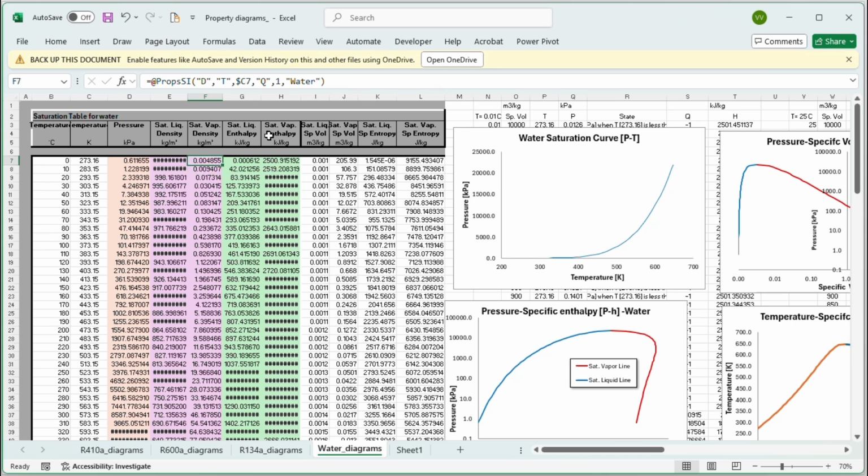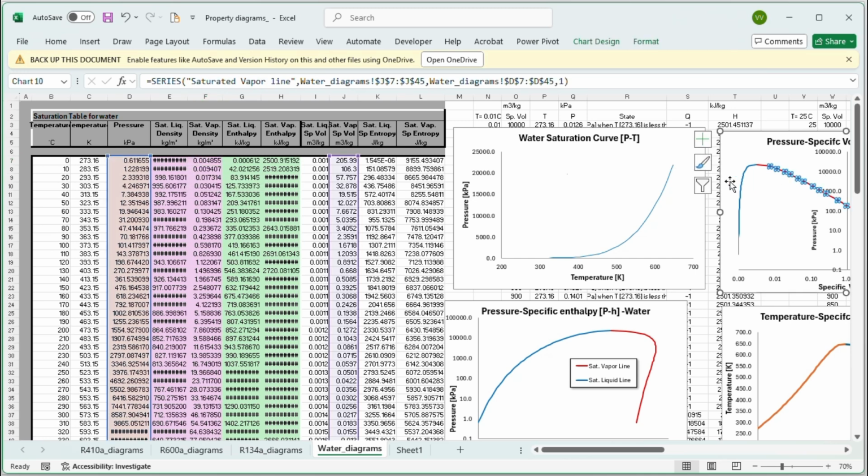And for liquid you choose a quality of 0. So temperature and quality, and the quality matters in this case. It's not like pressure. The specific volume is different for liquid, different for gases, and different for the mixture. So you create this red line by only calculating the specific volume of vapor.